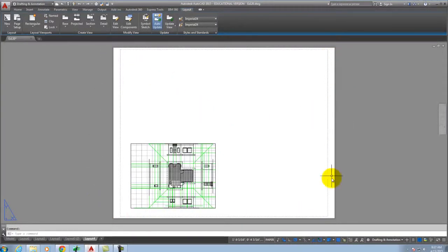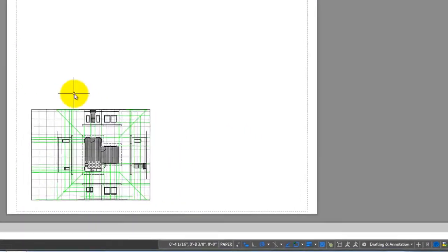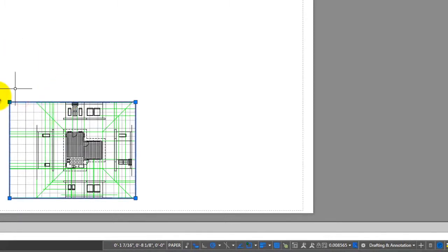And so this is now the C size sheet of paper. It's 17 inches on this side and 22 inches on this side. Okay? So if I went over to the printer and I plotted it, this would show up exactly what I see. Now, inside of this paper space, we have the ability to have what are called viewports. And these viewports are designed such that these are going to be where we do the scaling. And we can have as many or as few as we want on this particular page.